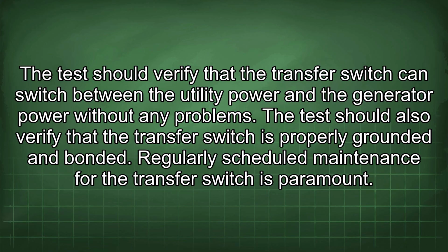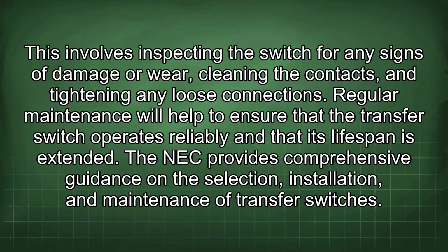Regularly scheduled maintenance for the transfer switch is paramount. This involves inspecting the switch for any signs of damage or wear, cleaning the contacts, and tightening any loose connections. Regular maintenance will help to ensure that the transfer switch operates reliably and that its lifespan is extended.